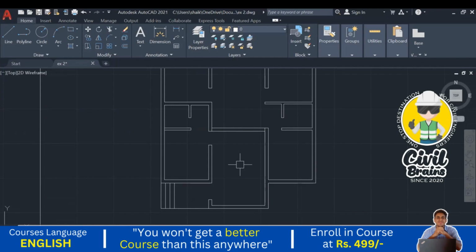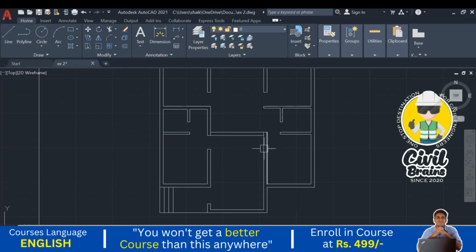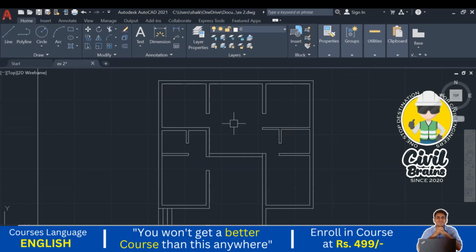Okay, so now where we need to provide the windows. Always remember, for whichever outer walls there are, for those outer walls we are providing the windows. We are not providing windows for the interior walls. Always remember that. What are interior walls here? Say you enter the living room or drawing room here. For this wall we can't provide a window. For this wall we can't provide a window. From interior walls we can't provide windows. Only for the exterior walls we are providing the windows and the ventilators. That is the first step. You just remember that.